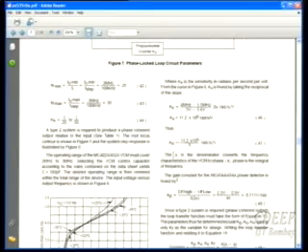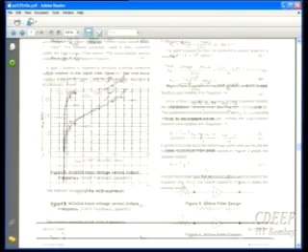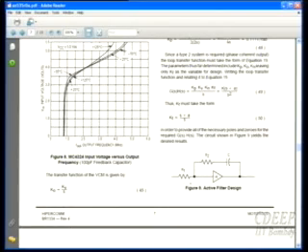And then again, similar, of course, here instead of having a real VCO, they have ICs, and an IC has its own characteristic, for example, voltage versus frequency. Therefore, they choose these plots to choose values. So you look at this. One thing I wanted to tell you, they have used an active filter, okay, instead of a charge pump.